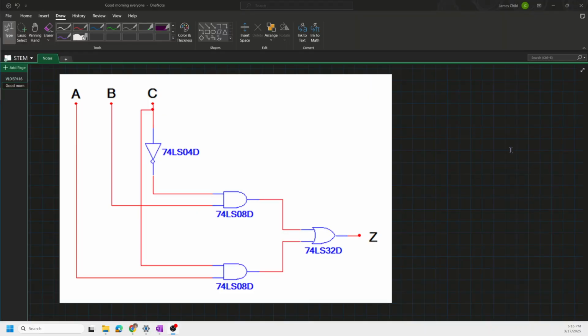The next thing I want to show you is kind of a shortcut that one of my teachers taught me. And this is called bubble pushing. So what we do, we put 2 inverters in series here. So we're going to put an inverter here and an inverter here. But instead of drawing out the inverters, we know that the circle denotes an inverter. So I'm going to do 2 inverters, 1 here, 1 here, 1 here, and 1 here.